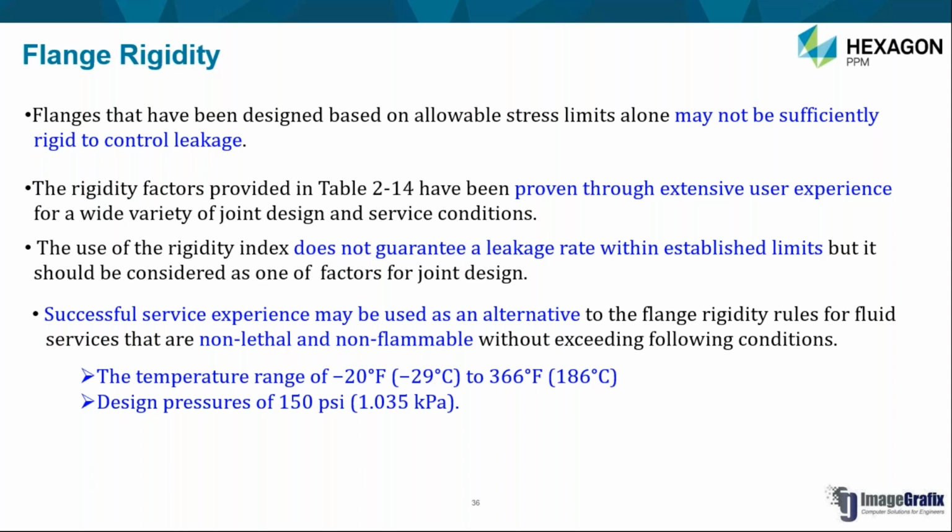What the code is saying is successful service experience may be used as an alternative to the flange rigidity rules for fluid services that are non-lethal, non-flammable, without exceeding the following conditions. So the main condition is that the process requirement is non-lethal and non-flammable. If those are lethal and flammable, then it is mandatory to consider the flange rigidity. And if you see over here, there is a limit on the temperature. The temperature should be within the limit of minus 29 degrees centigrade to plus 186 degrees centigrade, and the design pressure should also not be more than 150 psi.